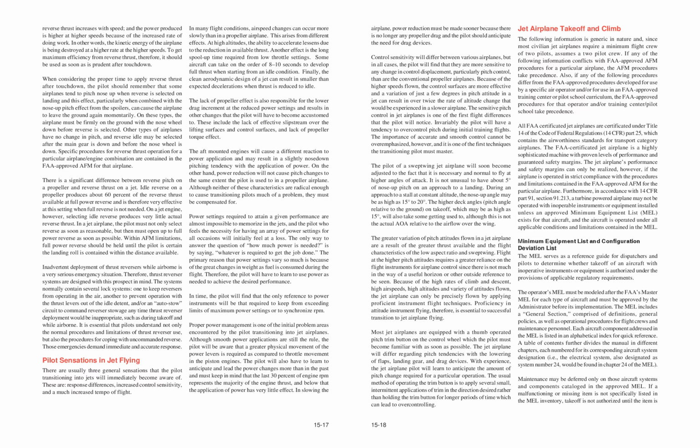At high altitudes, the ability to accelerate lessens due to the reduction in available thrust. Another effect is the long spool-up time required from low throttle settings. Some aircraft can take on the order of 8 to 10 seconds to develop full thrust when starting from an idle condition. Finally, the clean aerodynamic design of a jet can result in smaller than expected decelerations when thrust is reduced to idle. The lack of propeller effect is also responsible for the lower drag increment at the reduced power settings and results in other changes that the pilot will have to become accustomed to.